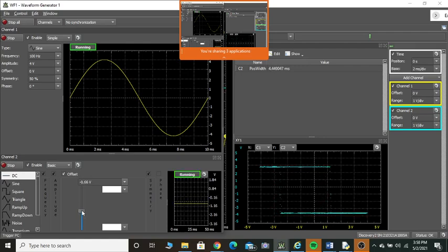Now here I am not changing the values of R1, R2. Keeping the same R1, R2 will keep this width the same. Can you see this is the hysteresis width? This hysteresis width will remain the same. Only VTH will move, and VTL will also move by the same amount. Can you understand what's happening if you increase the reference voltage? Can you see the width from VTL to VTH? Does it remain constant? This hysteresis remains constant. Only VTH and VTL will change.